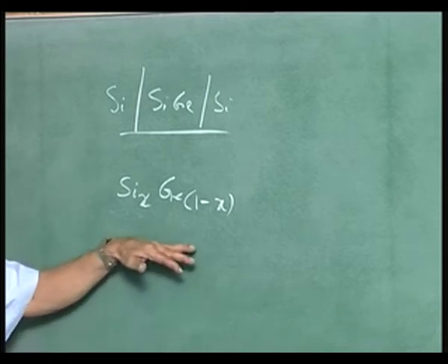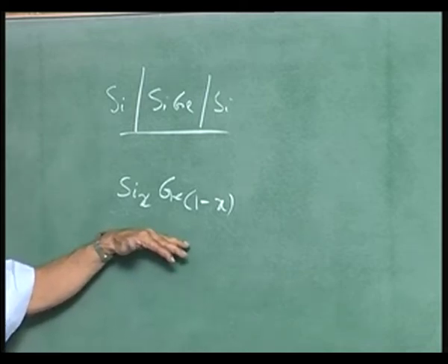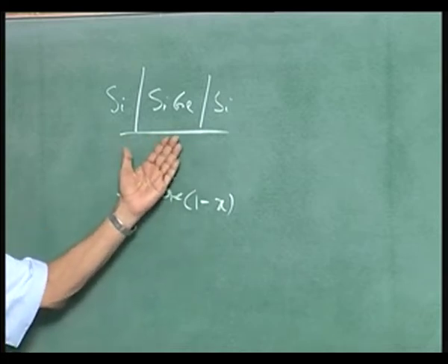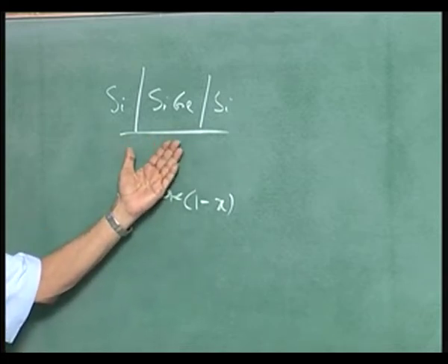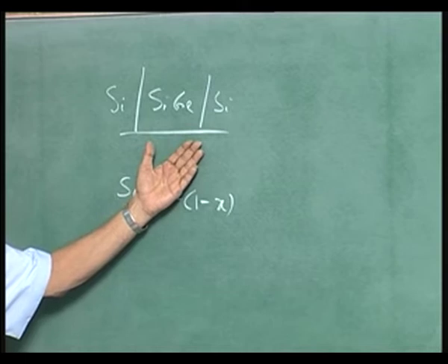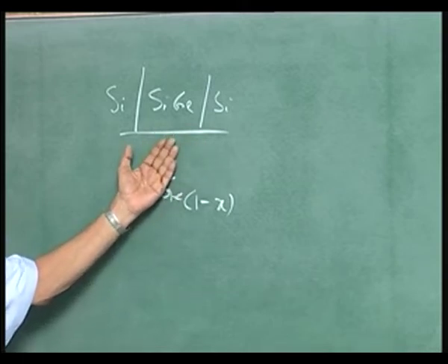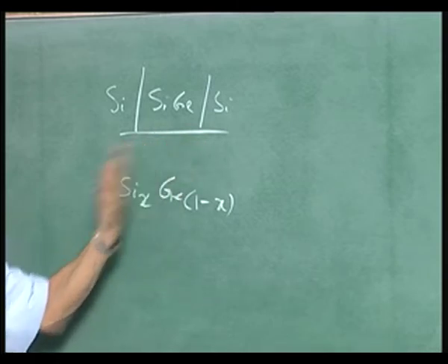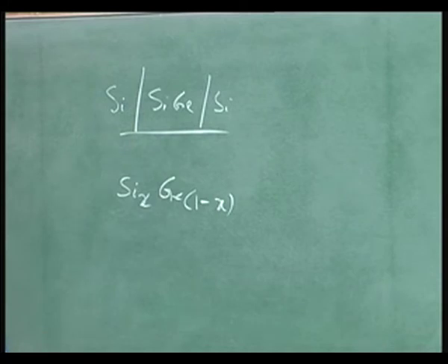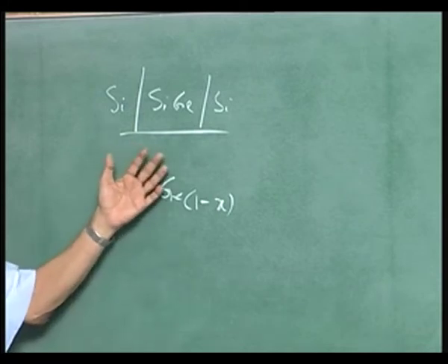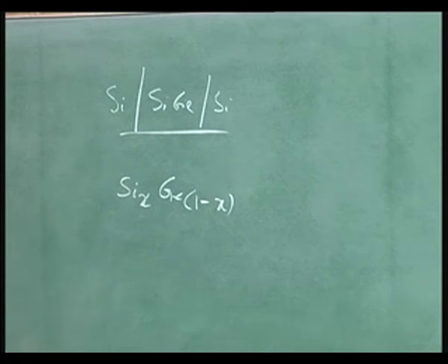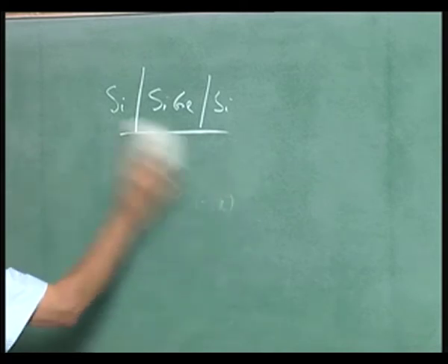But it is very popular, not for high electron mobility transistors. Neither of them has high electron mobility. Silicon 1500, germanium 3600. Silicon germanium will be in between, but you will see that this is suitable for making bipolar transistors. Okay, now let us just go back and see.